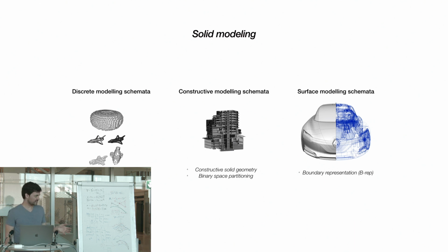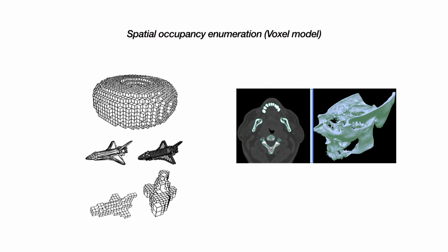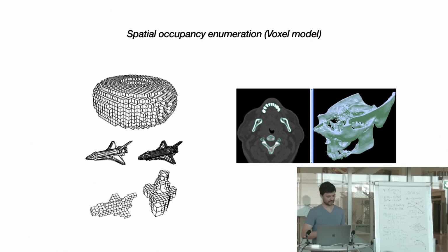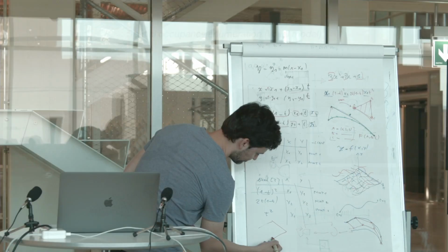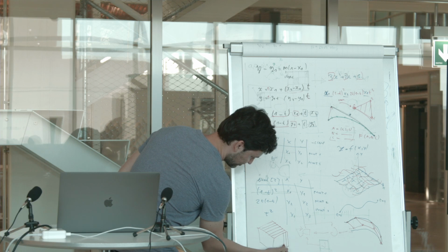But solid modeling is not a simple schema. It can be implemented in different ways, so let me show you how this was done. The simplest schema used to model solid objects is based on the idea of spatial decomposition. In the simplest implementation, you take the representation of three-dimensional space and subdivide it into discrete elements of pre-specified size, and this becomes a three-dimensional lattice. You take space and practically extend it in all dimensions into a box of cubes.